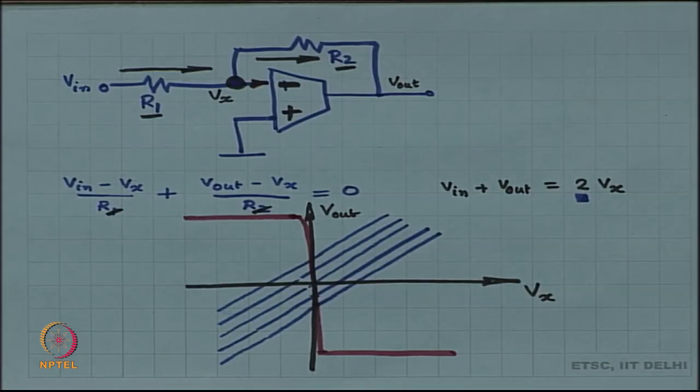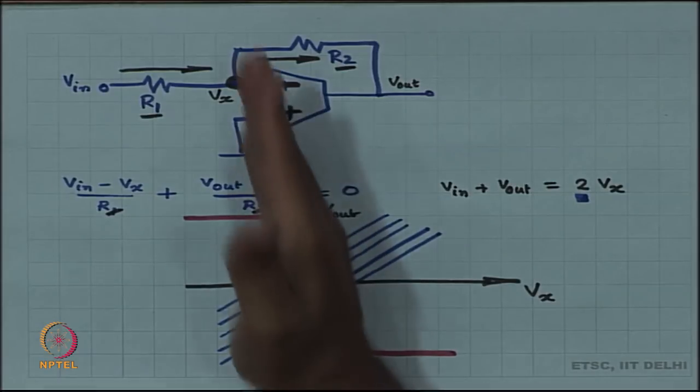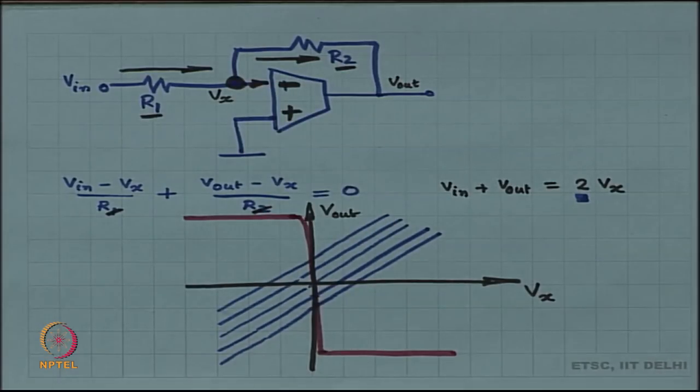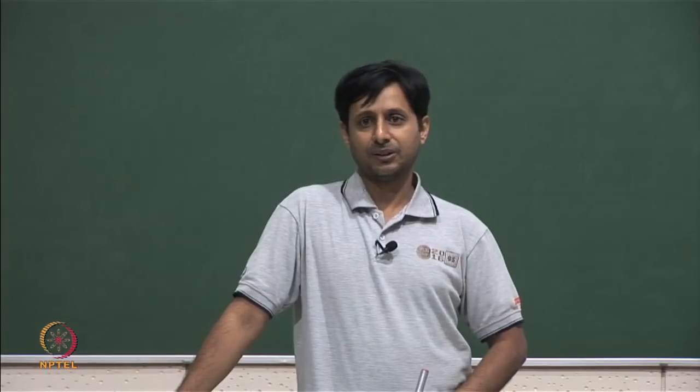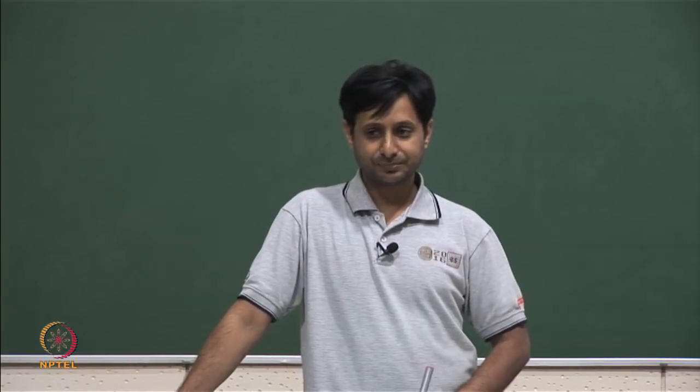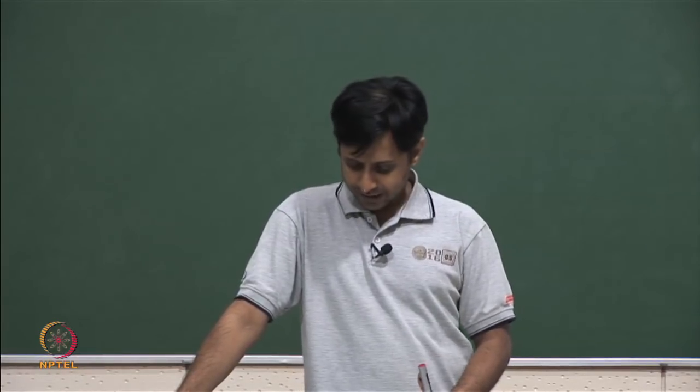Okay. And the gain of this, that is the slope of this in this transition region, is minus 10,000 in this case, because you have designed the OTA or the op amp, whatever it is, with a gain of 10,000. All right, so far so good.